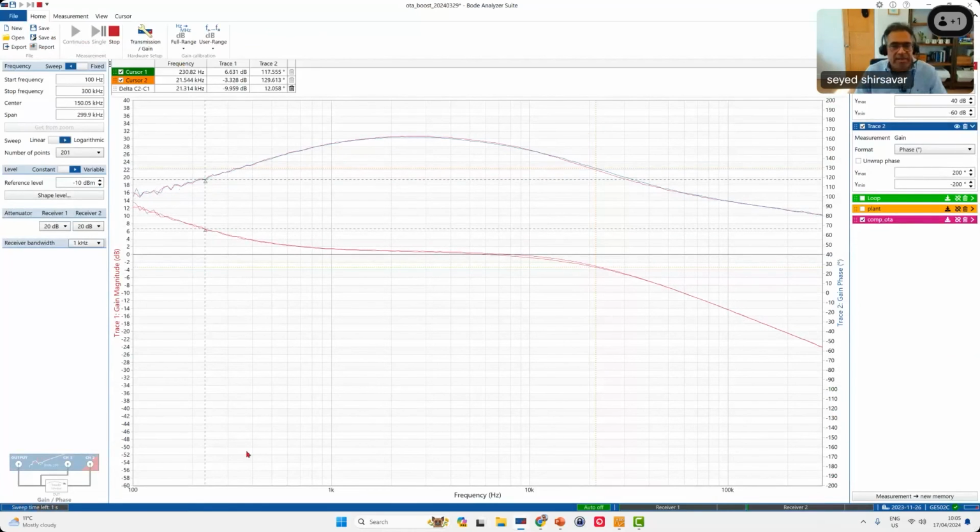Okay. So this is the compensator that I'm measuring on the boost converter that we just designed. And I'm going to now import that into WDS, and I'm going to superimpose it on the theory, and hopefully, fingers crossed, it's all going to meet. So save.